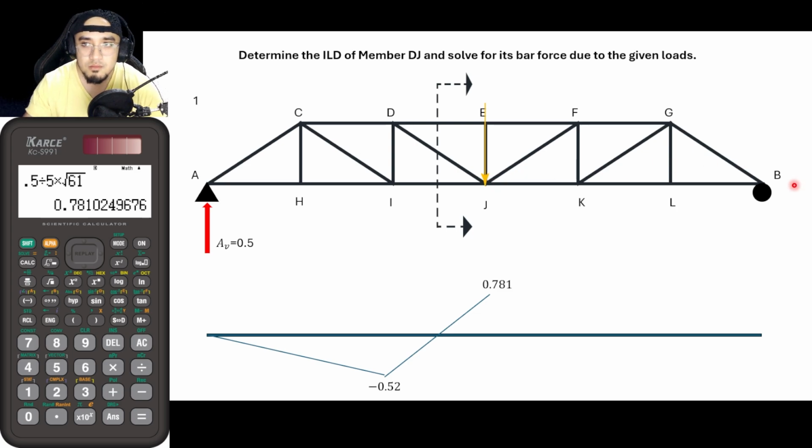If you want to know the values here, you could move this load to this joint, then to this joint, but I would rather move this load to the end already, since by my experience, this would just vary linearly. So I would rather skip EJ, or skip the unit load, and move it here already, because I know that the behavior would just be linear.